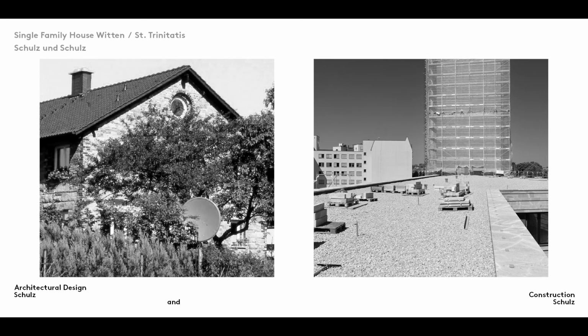In DIN 2761, the terms roof covering 363 and roof facing 364 follow the same principle as we saw in the previous film on horizontal elements. Roof coverings sit on top of the roof facings below it. The roof covering used depends on the pitch of the roof and the manner in which water is carried away. On pitched roofs, where rainwater runs away down the roof, tiles such as pan tiles are used as the roof covering. Flat roofs need protection against the water that accumulates on them.